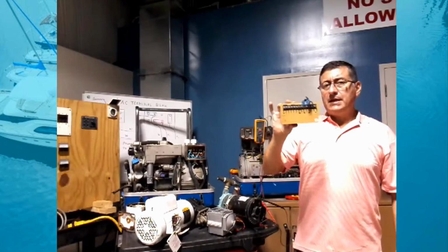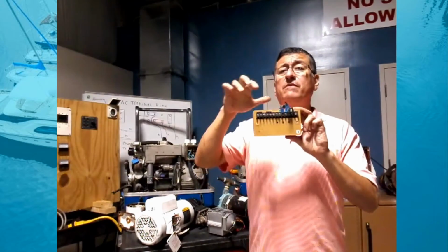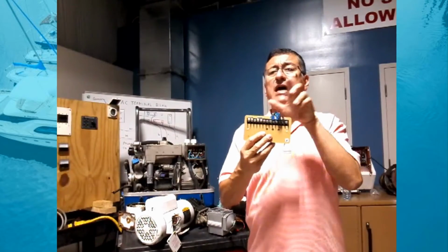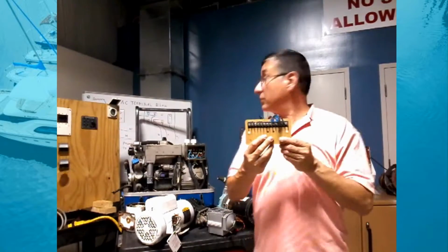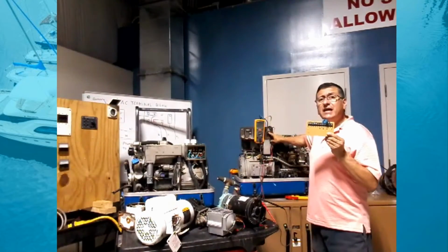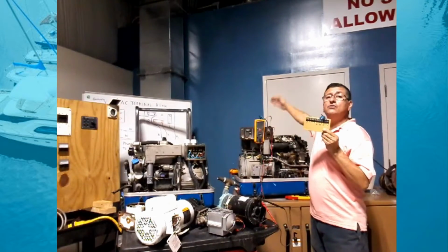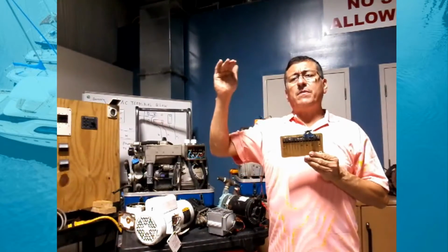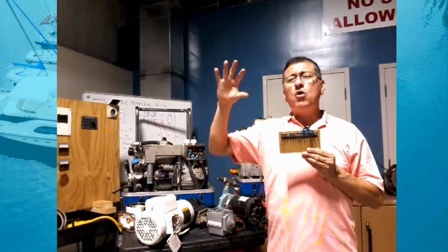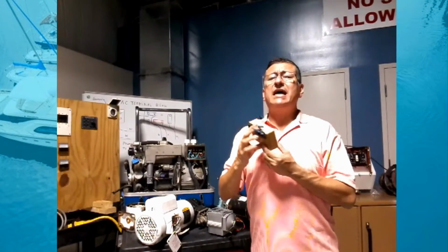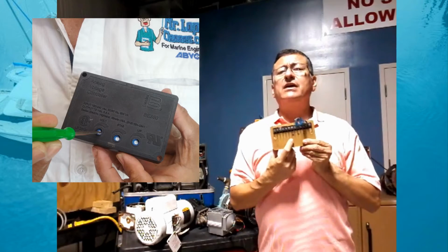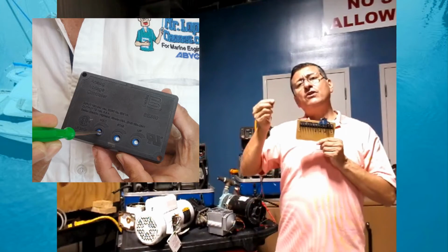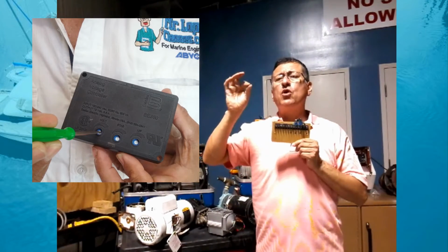Okay, this is the voltage regulator. The power coming from the back end enters here. The regulator regulates the voltage, and the power goes out into the breaker of the generator. After that, the power, hot, neutral, and ground, goes into the AC panel. If the increment or decrement is around 10%, you can adjust with a small screwdriver in the first spot. The first spot is volts. This is to calibrate high or low voltage if the deviation is no more than 10%.